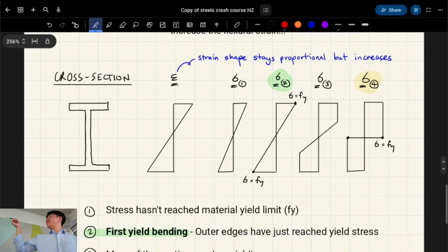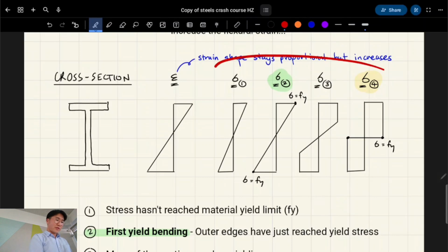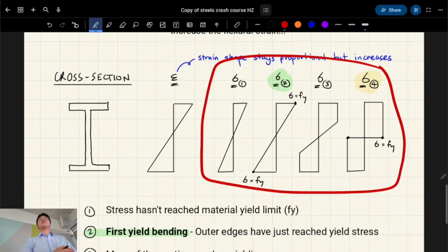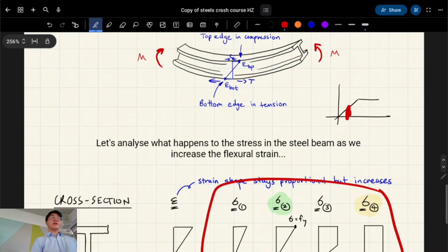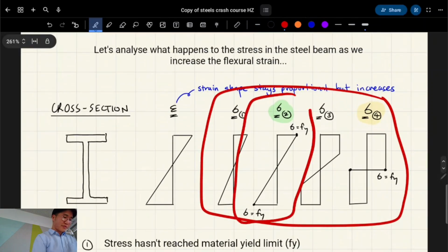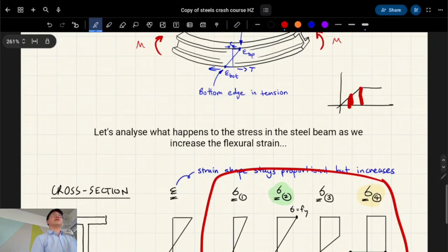So we're looking at different stages of stress here, okay? Essentially we're straining the beam by bending it more and more, right? And what's happening with the material curve? It's becoming more and more plastic. Yeah, exactly. So what's happened in this very first one? It hasn't yielded yet. So on our material curve, we're like here or something. What happens here at stage 2? It's the yielding point, at the yielding strain. Yeah, exactly.